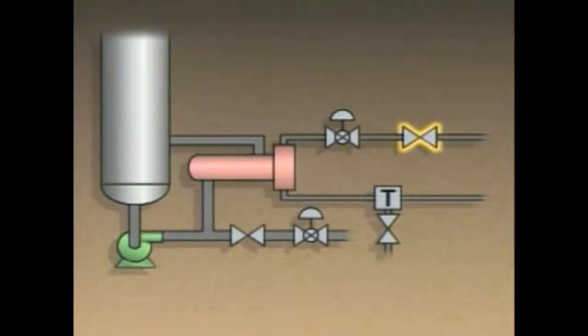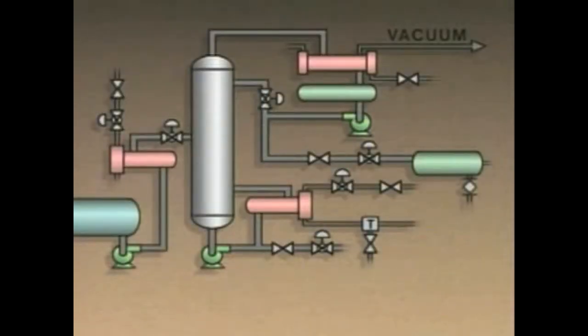An isolation valve in the steam line is closed as well to ensure that no steam reaches the reboiler. The reboiler circulating pump is left on for now to help cool the liquid in the equipment. At this point, there's no feed going into the column, and the overhead and bottoms mixtures are being recirculated.